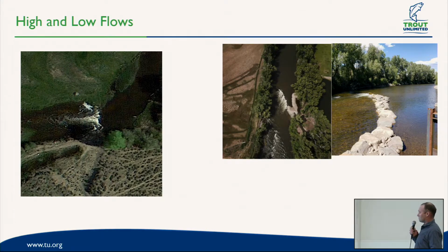For example, this is on the Gunnison River. They say 2018, really low flow period, they had to put additional rock out there to get water into their head gate, and then you get a high flow situation, and it creates some erosion on this bank over here, and it actually caused some blowout issues on this ditch just by choking down the channel and sending all that velocity towards the opposing bank. So there's a lot to deal with.